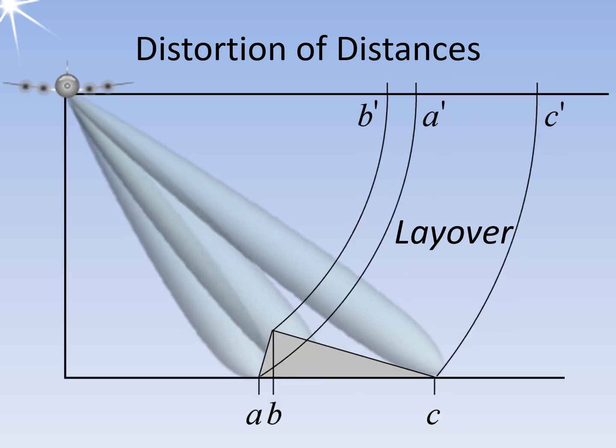A layover occurs when the terrain is so steep that the distance, slant range, to the mountain top, point B, is shorter than the distance to the foot of the mountain, point A. In the radar image, the order of these 2 points is even reversed, showing point B in front of point A in the distance. The steeper the beam angle, the more likely this effect will happen. Therefore, when selecting the beam angle, it is important to balance the reduced resolution caused by larger distances and the overlaps resulting from shorter distances.